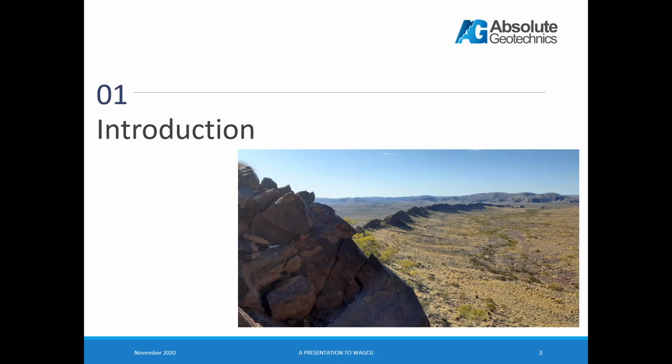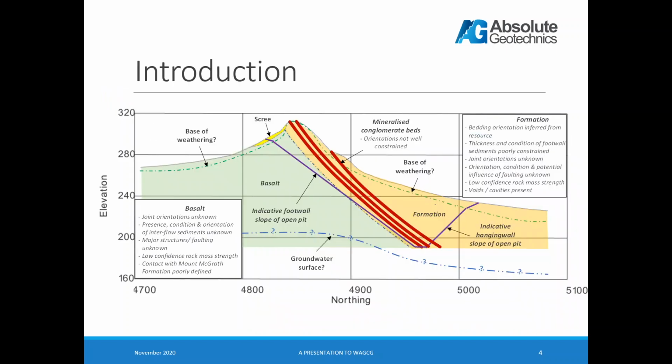That's a ridge of iron ore in the Pilbara, and it's a project I went to, and someone wants to mine it, but they don't want to drill any geotechnical holes. Why would you? I'm not saying that machine learning is the answer to that, but I came up with an engineering geological model. Cross sections are always great because you can pepper them with question marks, which is harder to do when you've got a 3D solid you rotate around. I haven't seen that kind of texture in Gem4D with question marks on it yet, which maybe is something I should suggest to France.